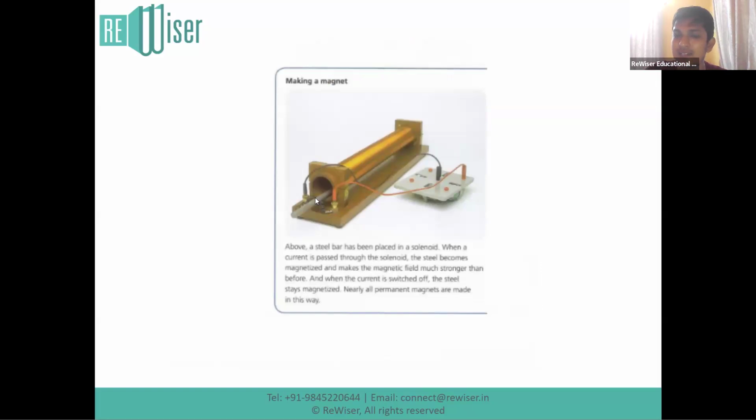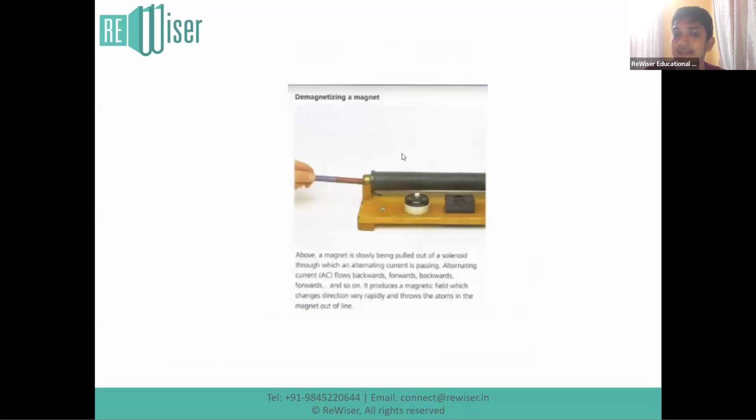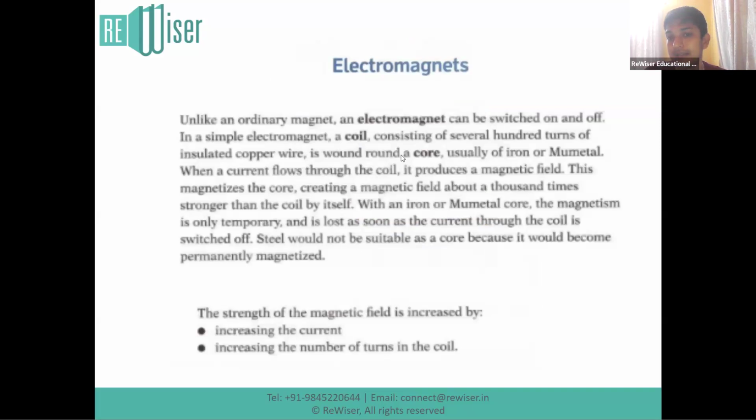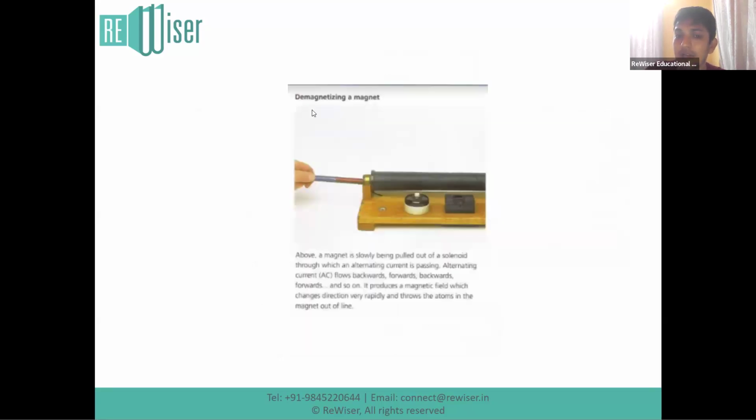This is an electromagnet. An electromagnet is just a coil of wire with a metal bar placed in the middle. What happens is, as current passes through the wire, it will start to produce its own magnetic field. This magnetic field will magnetize the metal bar in the middle. The magnetized metal bar will then behave as an electromagnet. That's it. So how do you increase the strength of an electromagnet? Increase the current, increase the number of turns. Reversing the current will reverse the poles of the electromagnet.